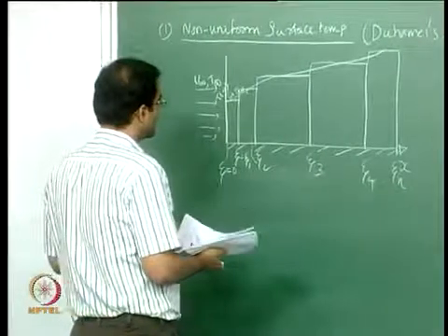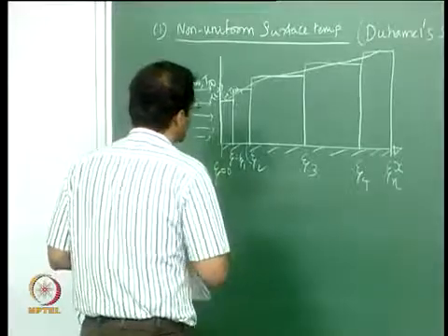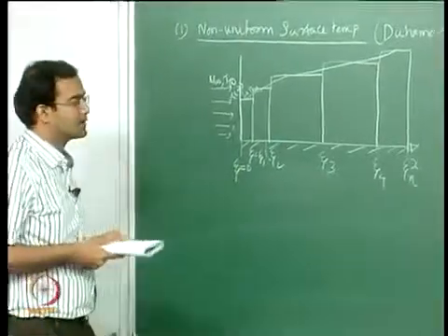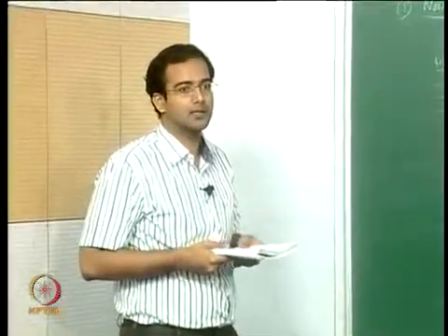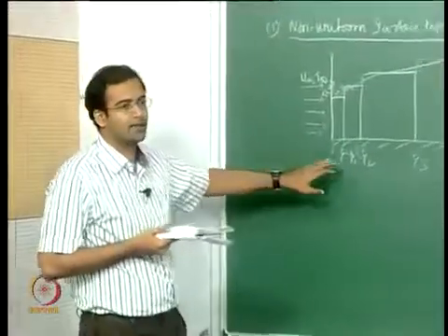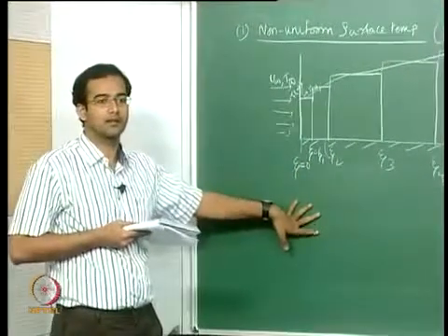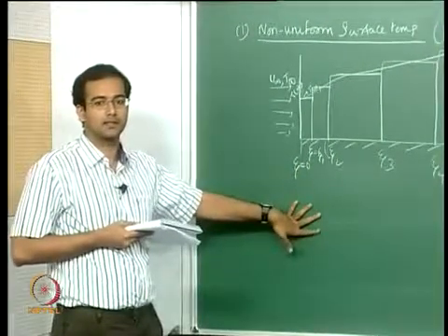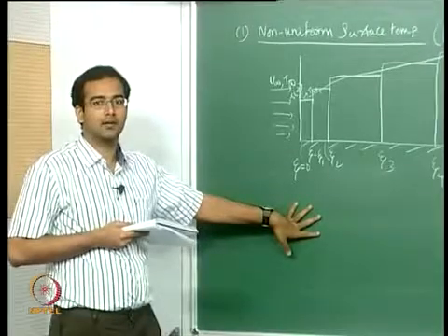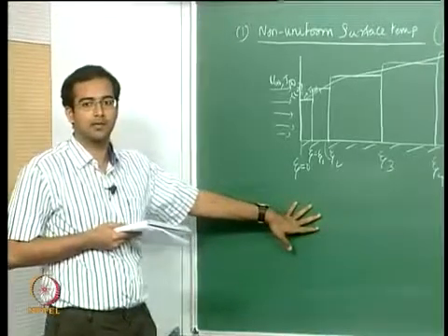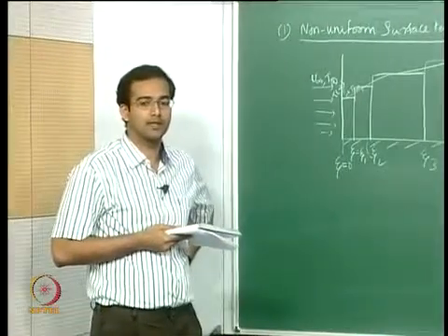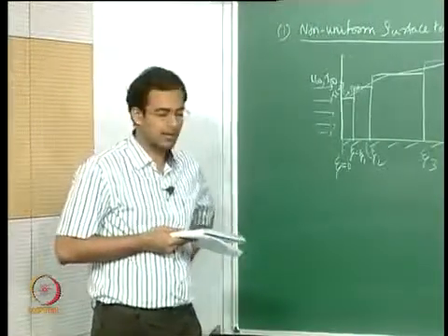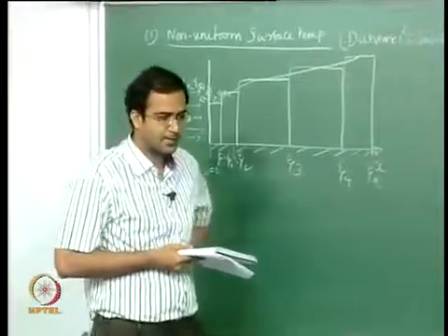So for this, how do we approach the problem? Thankfully, the energy equation that we are solving is linear once you know the corresponding velocity profiles. The velocity profiles are not going to get affected as long as your properties are not affected by the temperature. So your velocity is decoupled from the temperature and you can plug the value of velocity at a location into the energy equation, and your energy equation becomes quasi linear.